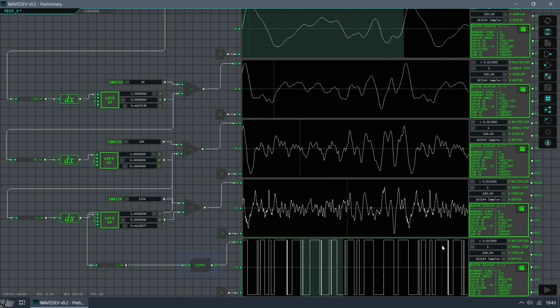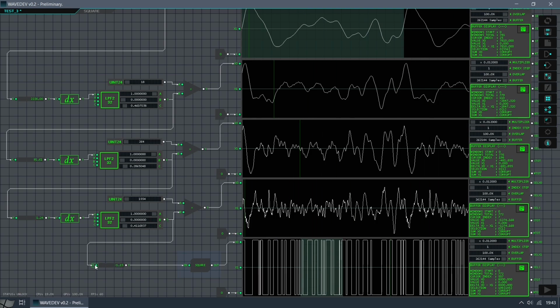If we apply infinite gain to the output of the third filter, we get this. It seems to be a better result than the previous one if we consider the same logic. But it is not. There are 3 reasons why you should avoid saturating these high components. First, they are too weak and close to the noise level. You can see here the multiplying factor that I am using to match the size of this signal with the clean.